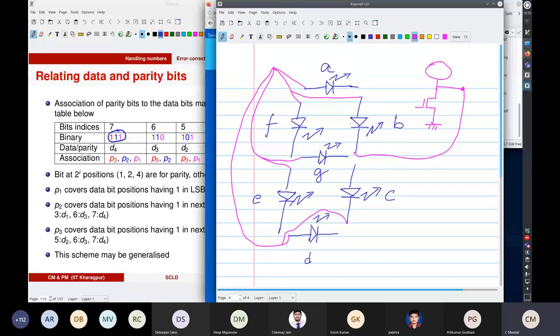So this gate will control this LED. So that means this is, say, VDD. All right. So if you want to light up this LED, you should provide a path to the ground. That means the output should be 0. This output should be low if you want to provide a path to the ground. That is one of the ways in which it works.